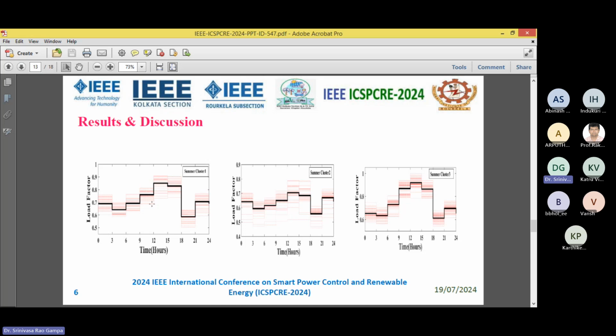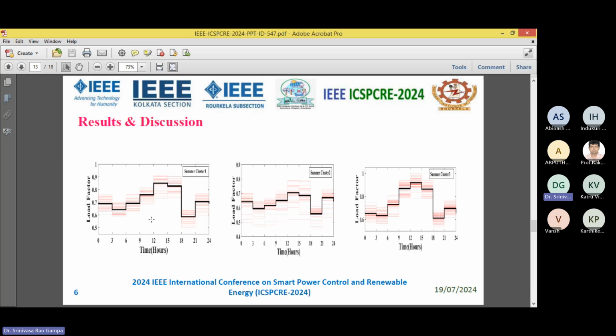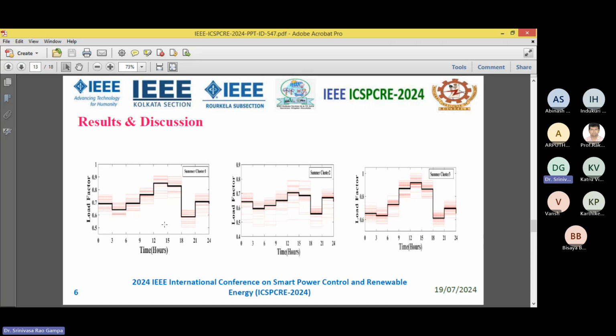Here the renewable energy will be different, for meeting the required voltage and power loss requirements, especially the voltage requirements. To meet the voltage requirements is more important, because sometimes the renewable energy will be less, sometimes it will be more. Those requirements we can estimate cluster-wise. In general, what the literature does is consider the average summer value, average winter value, or average rainy value.